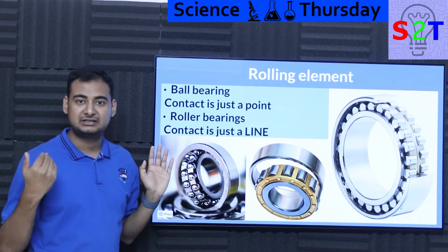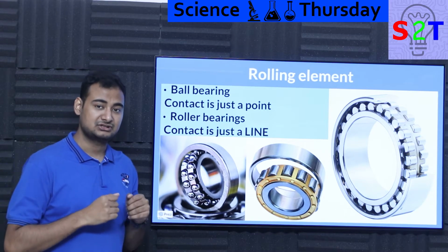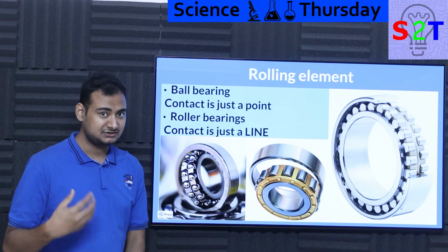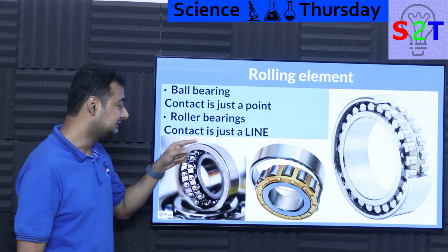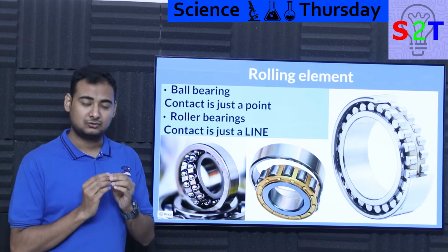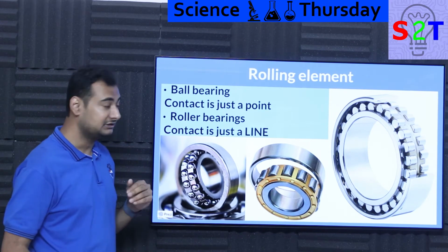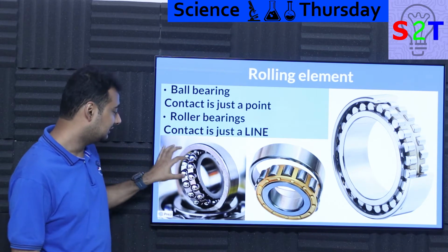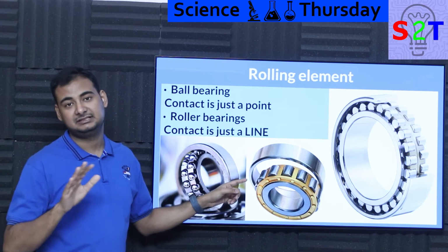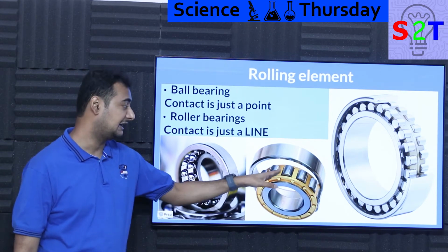But if you are talking about a scenario where you have to use heavy loads, basically something that is really heavy, like a freight car or railway locomotive, things with a serious amount of loading, then you have to utilize what we call roller bearings. The primary reason is that roller bearings are cylinders, so the contact from a cylinder is a line. In a mathematically perfect world, a ball bearing will always have a point of contact, while cylindrical bearing elements like rollers will have a line contact.